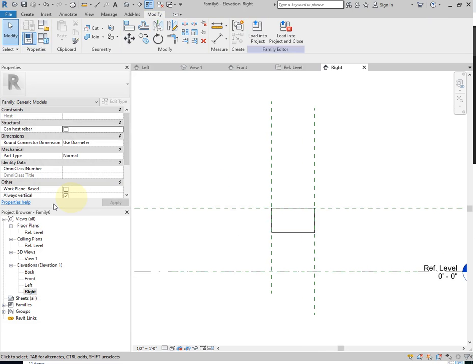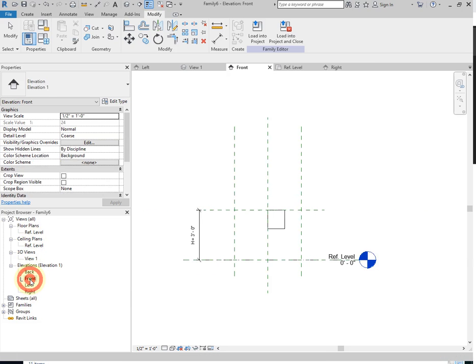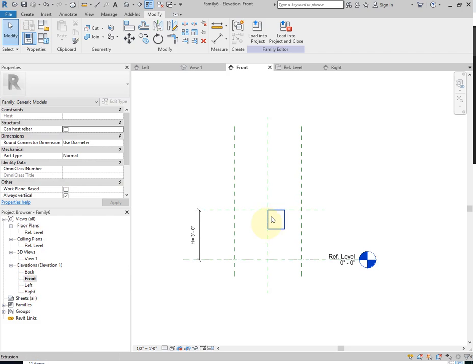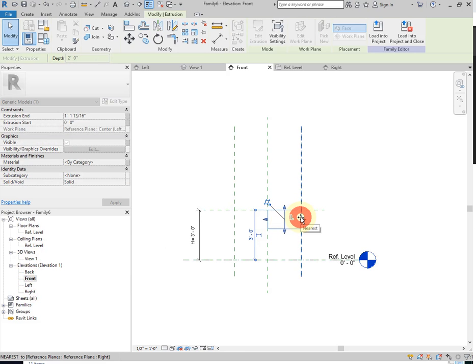Now we want to put maybe 2 little narrow rectangular legs on the side of the thing. Let's go to our front. Now I'm looking at the front here. I see the thing's not going to the 2 planes on the left and right. So I can drag this one grip till it snaps to one of the planes and let go, and I see a padlock.